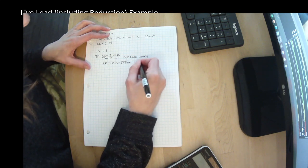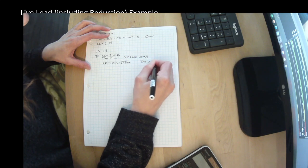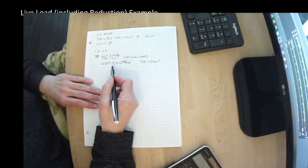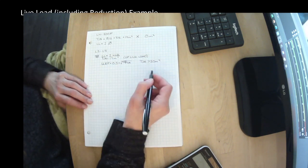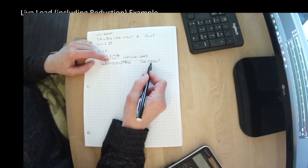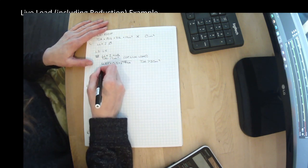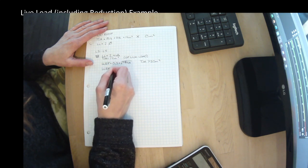But the tributary area had to be greater than 20 meters squared. What does that make our live load reduction factor? It doesn't make it 0. We only have 14 meters squared, and we need at least 20 meters squared to have a live load reduction factor. So what we're really saying is our live load reduction factor equals 1.